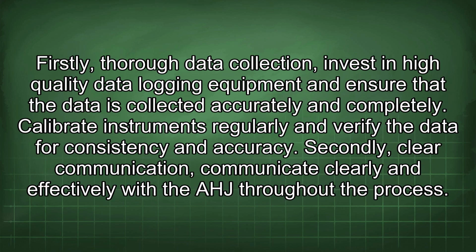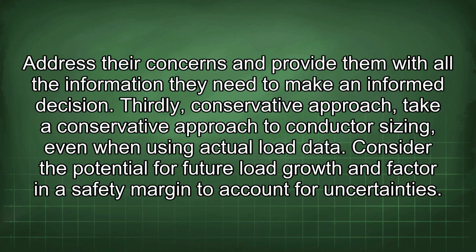Firstly, thorough data collection. Invest in high-quality data logging equipment and ensure that the data is collected accurately and completely. Calibrate instruments regularly and verify the data for consistency and accuracy. Secondly, clear communication. Communicate clearly and effectively with the AHJ throughout the process. Address their concerns and provide them with all the information they need to make an informed decision.